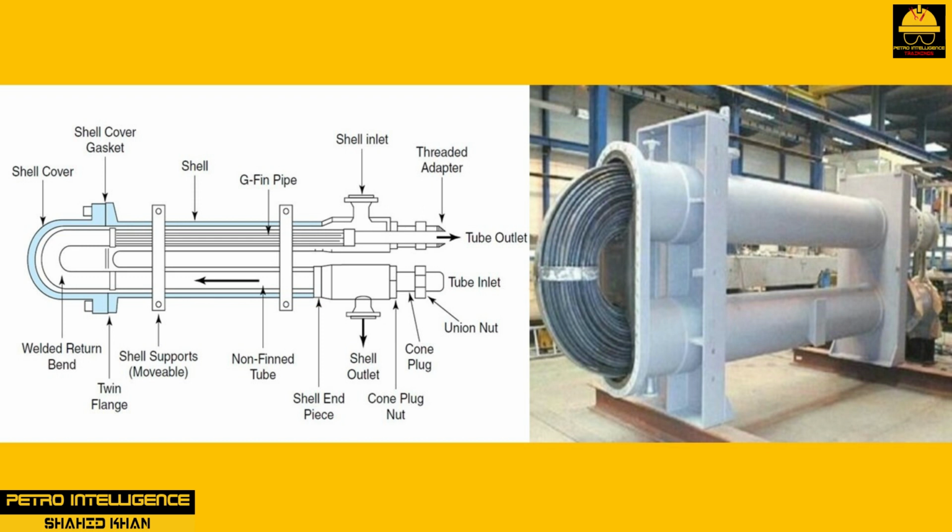Among its advantages are its excellent capacity for thermal expansion because of its U-tube type shape, its fin design, which works well with fluids that have a low heat transfer coefficient, and its high pressure on the tube side. In addition, it is easy to install and clean, its modular design makes it easy to add new sections, and replacement parts are inexpensive and always in supply. Among its disadvantages are the facts that it is not as cost-effective as most shell and tube exchangers, and it requires special gaskets.